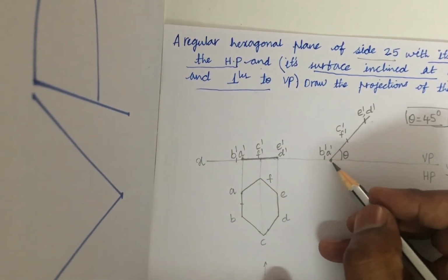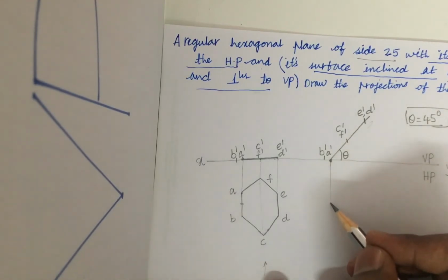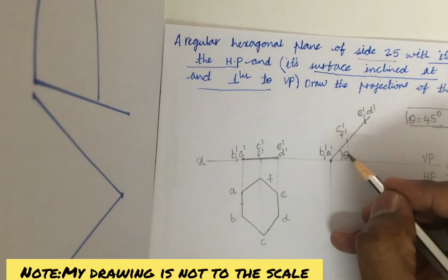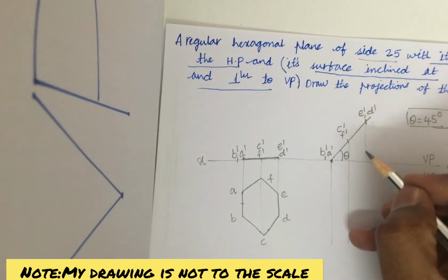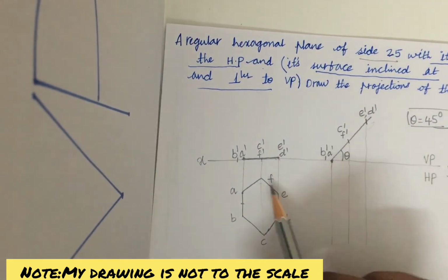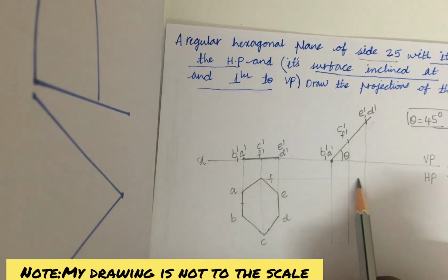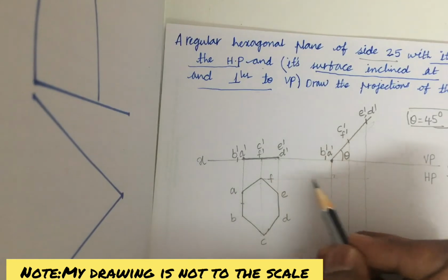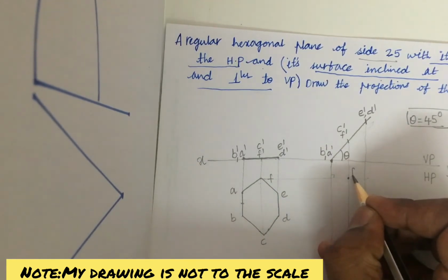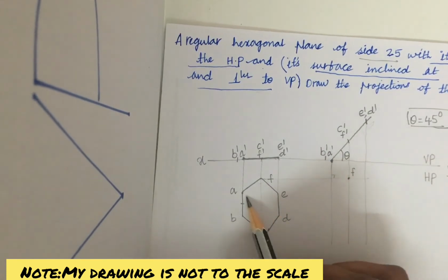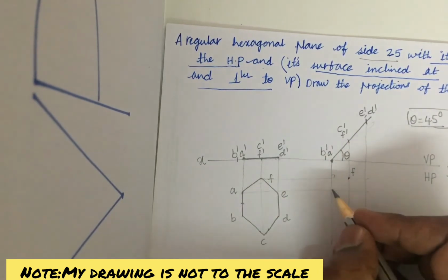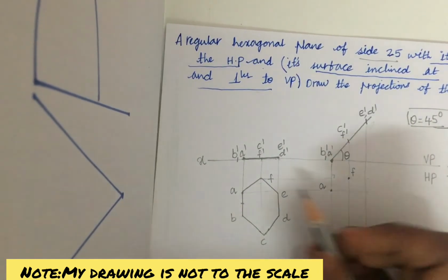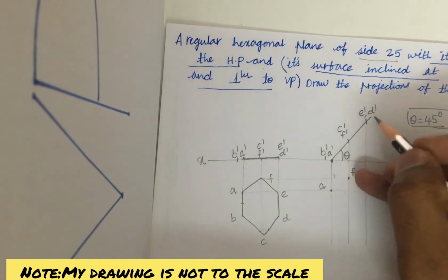So what we are supposed to do here is, after inclination, we are supposed to project the vertical lines from the line. All the vertical lines drop from here. Later, from the true shape, we are supposed to draw the horizontal lines. They are perpendicular to each other. By that statement, we can say that it is orthographic projection. So what is this point? The point of intersection is to be marked, and this is F. So this will be F along this. Later, A and E will be along the same line. So this is A along this, and A along this. And the point of intersection is A here, and E is also located on this, and E is along this.